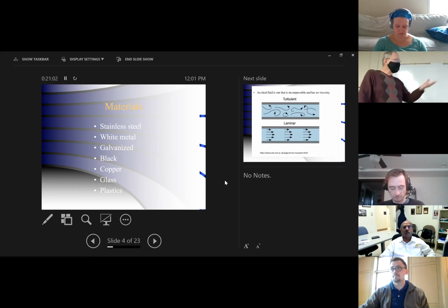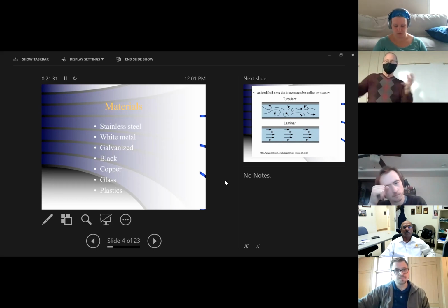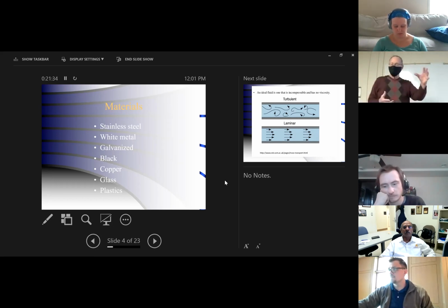Plastic type pipes of various types. If you're in the pilot plant, you've seen all kinds of hoses. You've walked in there and seen them moving from point A to point B. Best way to think of plastic pipe, it's a great way to have flexibility in your plant, but you do not want to put plastic in place as your sole piping type of mechanism. It works great in a pilot plant simply because you're trying to hook different configurations of equipment together day to day. Whereas in a typical plant, you're not going to see too much plastic.